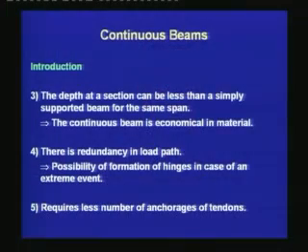Third, the depth at a section can be less than a simply supported beam for the same span. That means, given the same span and given the same load, if we use a continuous beam, it will have a reduced depth compared to a simply supported beam. This implies that the continuous beam is economical regarding the material.